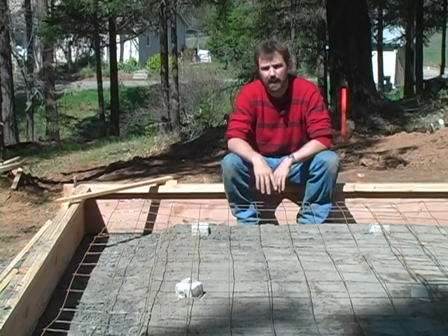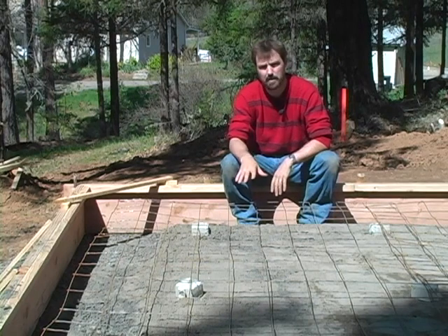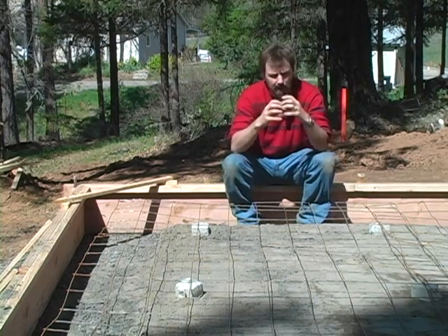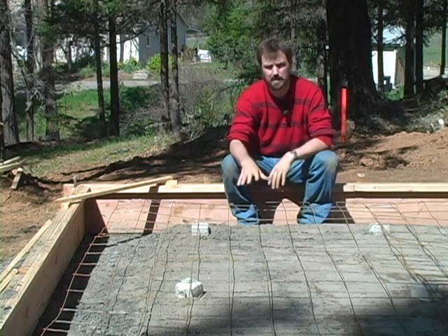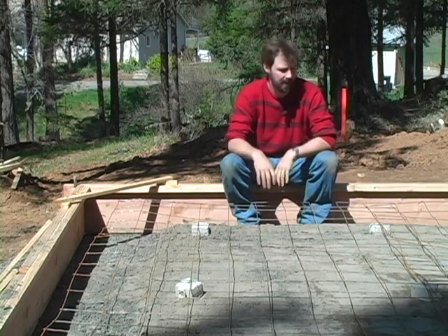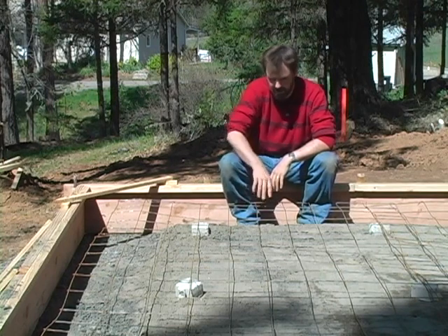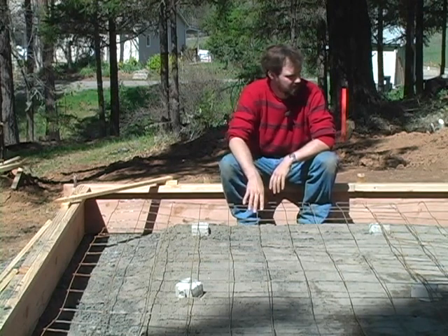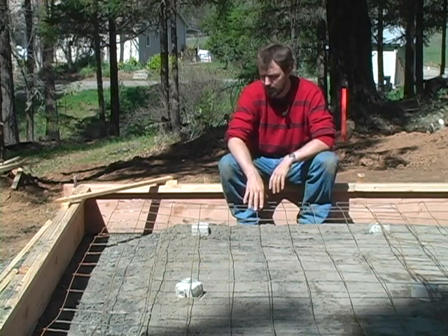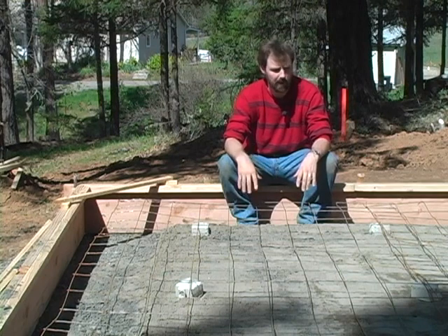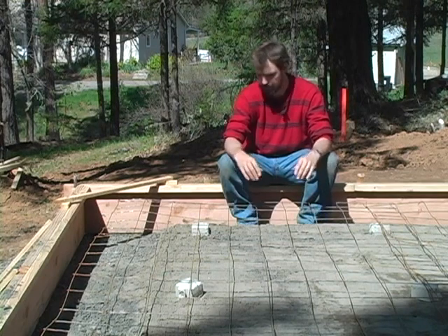In order to eliminate cracking in your slab, you want to put some kind of structural steel. Concrete has a great strength in the compressive direction, but in tensile strength it's very weak, so we use the steel to supplement the tensile strength of the slab. Now I'm using a welded wire mesh here as my structural steel. You can also use rebar. In this case, this is something you can use where you don't need any specialty tools. You just need some wire cutters and some gloves, basically.